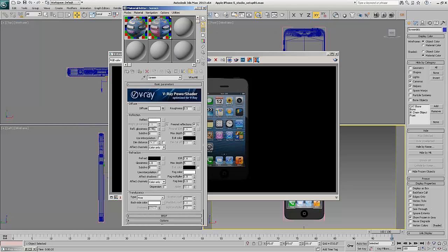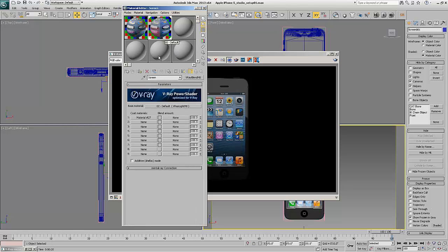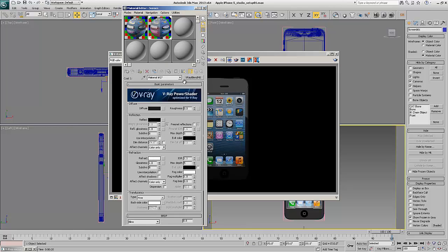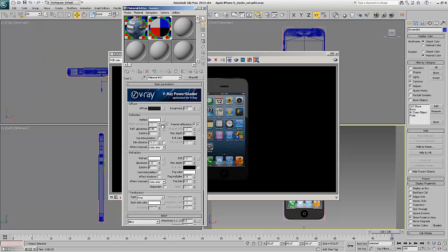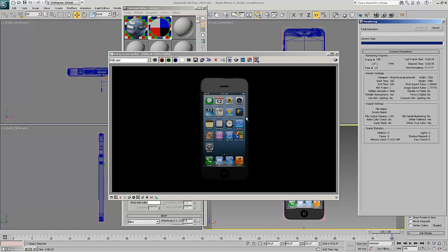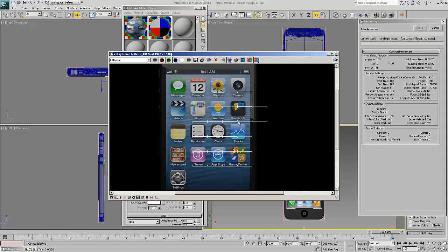And we're going to mimic his reflection here, so he's got a little bit of falloff and what have you. So let's do that, and we can just see our material here. So let's do that 0.95, and I didn't even have reflection on. Alright, and Fresnel. Okay, let's render that again. If we zoom in here, it's going to take a little bit longer, but now we'll see. Get a little bit more reflection. We had none in before, just refraction.